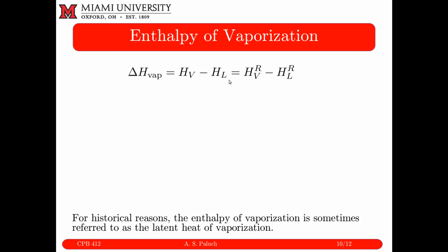So what I have written here as an equivalent expression is, if these are at the same temperature, I could take my enthalpy and write it as the sum of an ideal gas and a residual contribution. I could do that for both my vapor and my liquid phase. Well, my ideal gas term is only a function of temperature. So if both of these are at the same temperature, the ideal gas term conveniently cancels out.